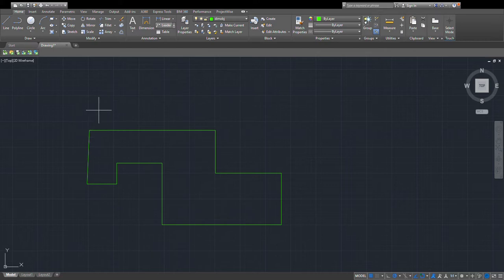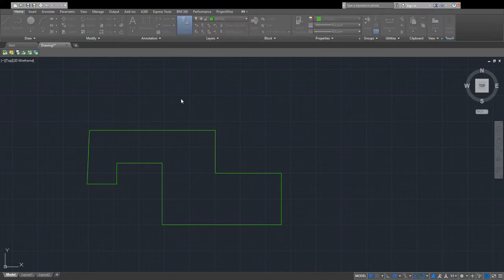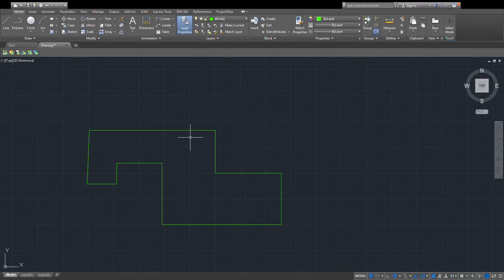As well, I'll tell you what, let me set up another layer first for our dimensions. New layer, call this dimension, change the color and make it red. Again, you should know how to do layers. It organizes your drawing and allows you to be productive and not repeat yourself over and over again. I'm going to double click to change it to the current layer. Again, green mark means that it's the current layer.